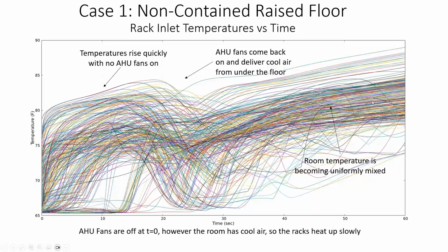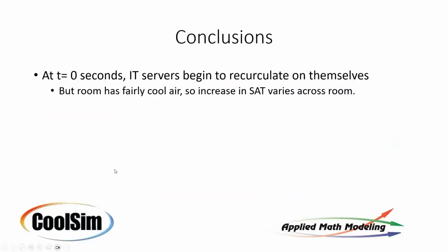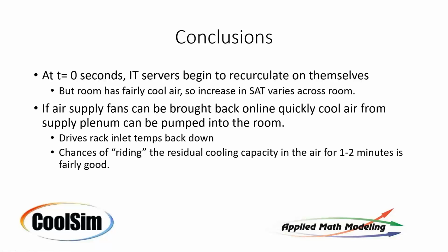So you basically got the fans running, you've got the IT servers running, and you're mixing everything in that room, and you get 60 to 100 seconds of time in a non-raised floor data center that's conventional. This is how things have been in the past. This is why many people have confidence that they're going to be able to make it through this transition, because this is what history has looked like in the past. When you talk to people about what you do in a transient case, they all go, yeah, well, we've been through one, it worked. Well, it may have worked before, but it's going to get tougher.